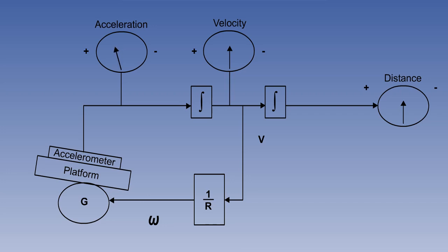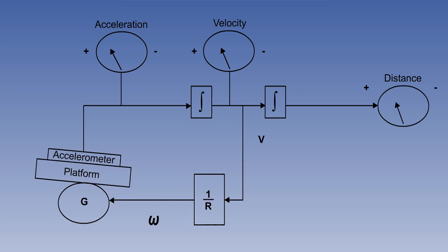So let's show this false acceleration on our meter. This acceleration will be passed to the first stage integrator, where it will be integrated into velocity, and then to the second stage integrator, so that it will be integrated into change of position. At the same time, the velocity is passed back along the V over R feedback loop. The system can't tell that we are still on chocks, and this is a false velocity, so it assumes that the aircraft is travelling around the curvature of the Earth, and slowly brings the platform to the level, which means that the source of the false acceleration is removed.